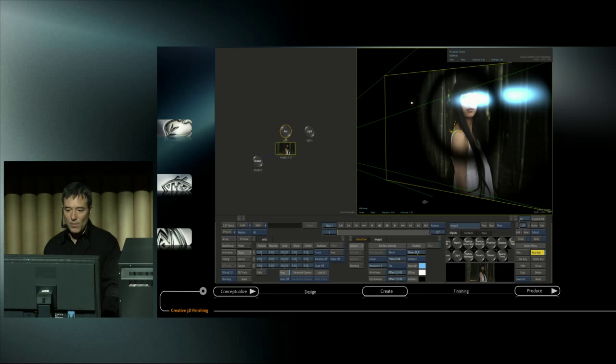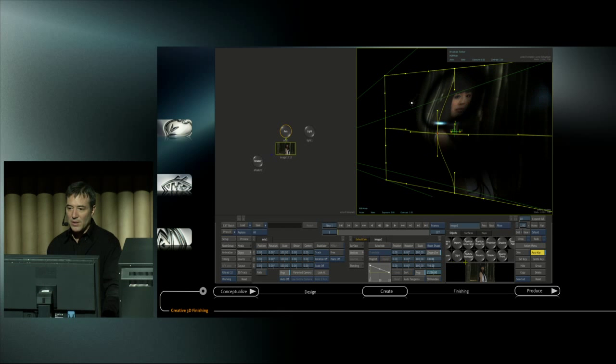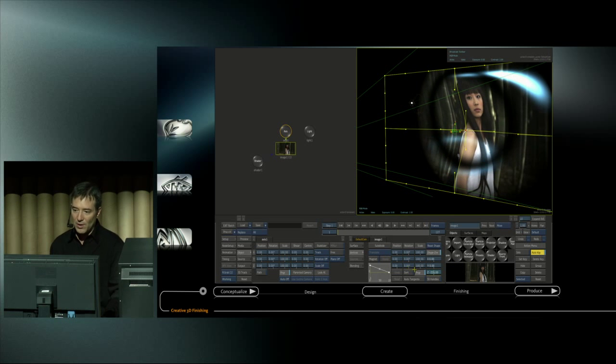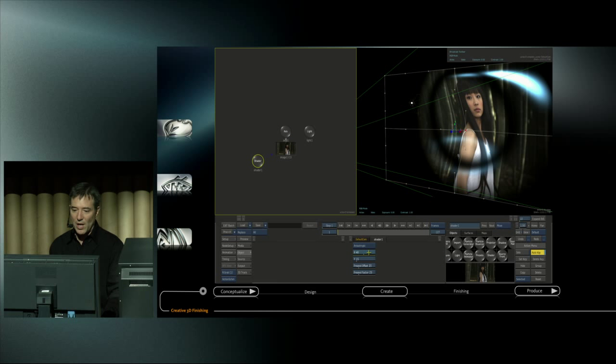If we go back to this surface and even turn it from a flat surface into an extended bicubic, I'll subdivide that surface, grab this handle. You can see as I bend that around, just exactly how the shading is actually going to affect that. And again, go back to the shader. You can see that the quality, the adjustments, it almost looks like you have a glow effect on the surface.